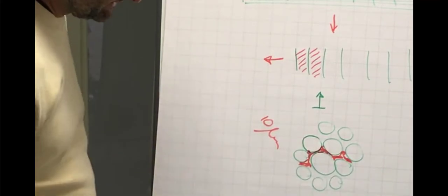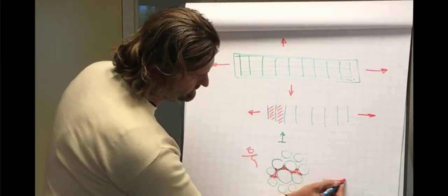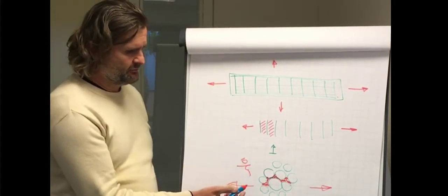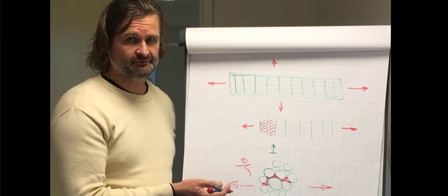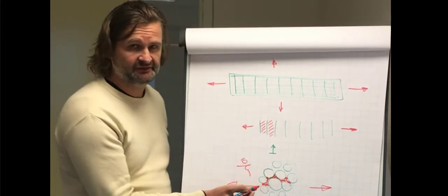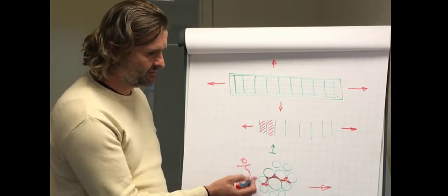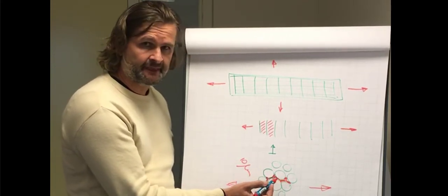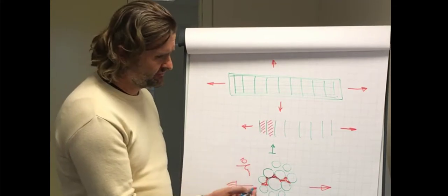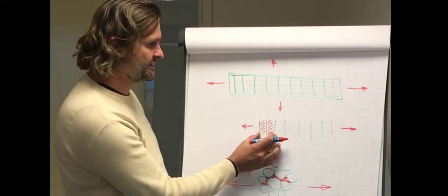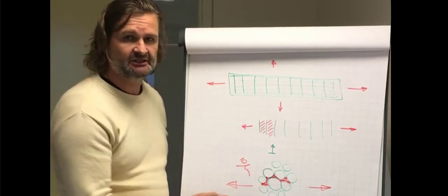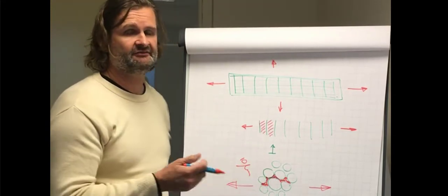This means that if we want deformation in the same direction, so I'm putting on the same load again, we're asking this layer to deform, and we're depending on the resin to allow for that deformation. But there's only very little resin to do that. So the flexibility of this layer is a combination of the flexibility of the glass and the flexibility of the resin. So even if I were to make the epoxy resin a lot more flexible to allow more deformation and therefore to allow more load, I'm only using maybe 20% in the total bulk of the material of that flexibility.